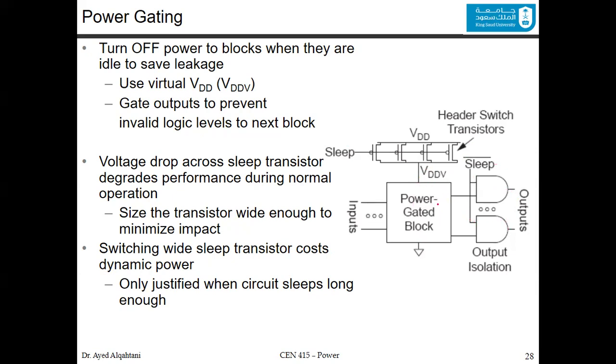Now, if you don't care about this block and you don't want its output, what will happen? This will be completely closed, meaning it will be off, off, off, and off. All of them will be off. So you don't have a VDD here. This will happen if you have sleep equal to 1. If sleep is equal to 1, all of them will be off. There is no VDD powering the block, so it doesn't work and doesn't consume static power.